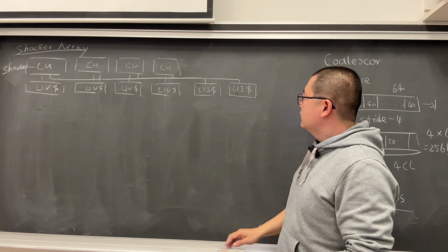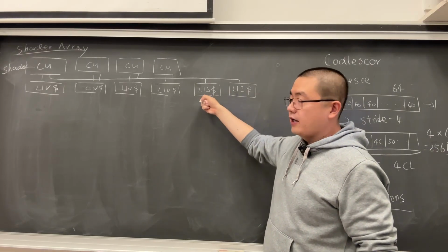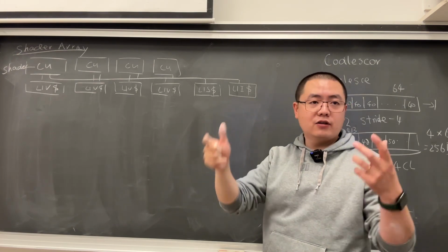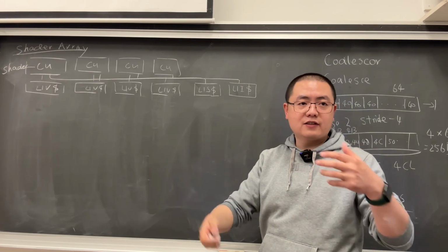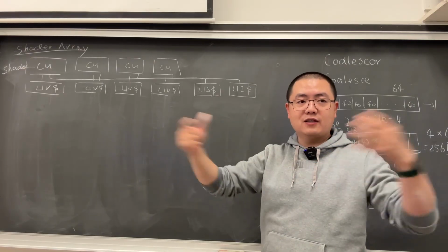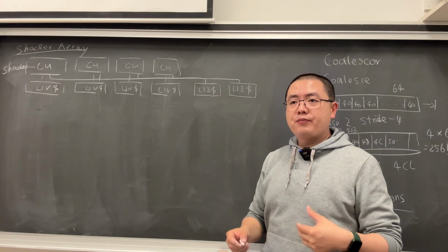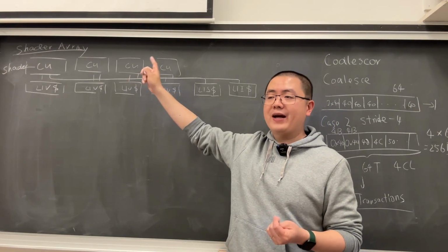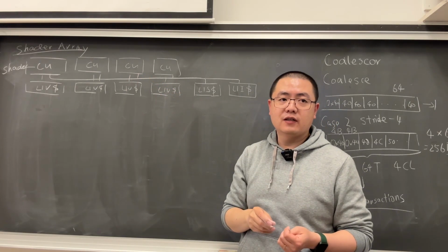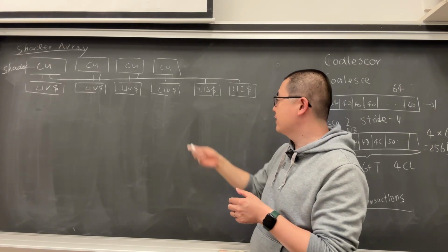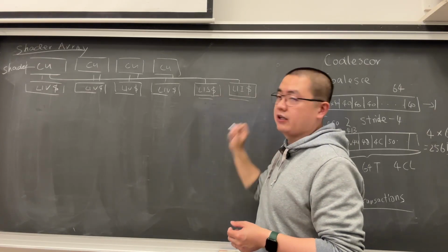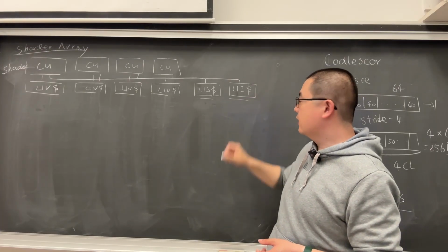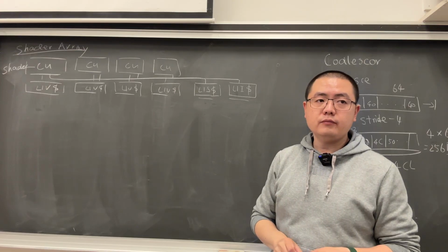So these are read only caches, and L1S is responsible for calculating addresses and loading things like kernel arguments and launch parameters, like the block size and the kernel size. These will not change, so every program, every thread will need that part of information. So it's better to be shared. That's why they are shared. And L1 cache is also larger, right?